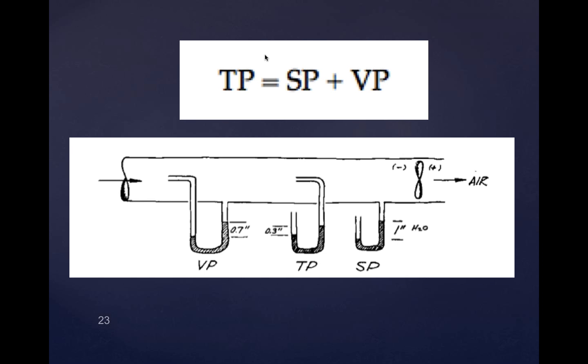Because the static pressure is going to be always a negative number, the velocity pressure frequently is not as high as the static pressure. Total pressure very frequently is negative. Interestingly enough, you exchange the two of them, basically you're equaling them out. If all things were perfect and frictionless in this system, the static pressure and the velocity pressure would be opposite numbers on the suction side, but they'd be the same quantity. Okay, but as we go through each transition, we lose some energy.